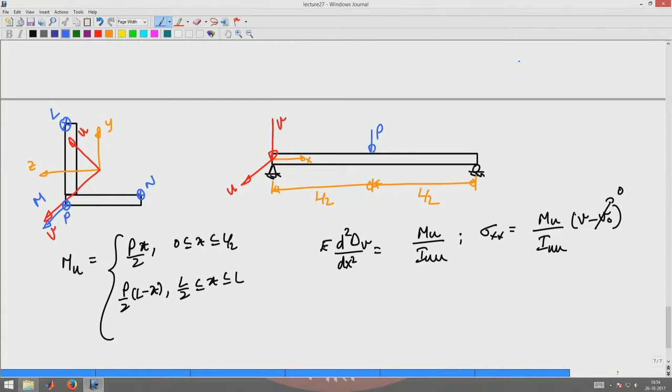Because of this force you can see that M would be in tension and L would be in compression. N also will be in compression because the point N is above the u axis, in the negative V direction. So from here you conclude that L and N are in compression and M is in tension in this case.